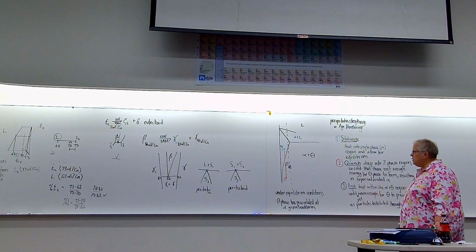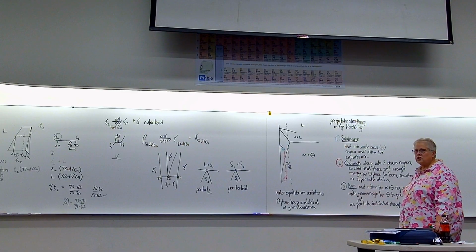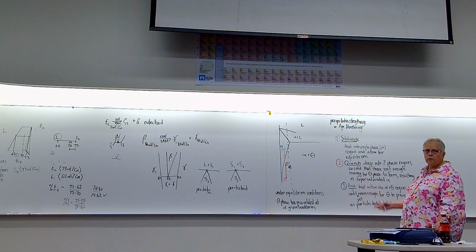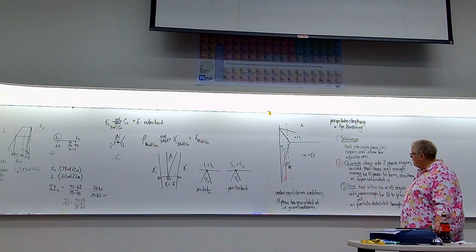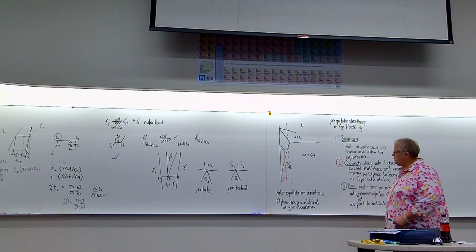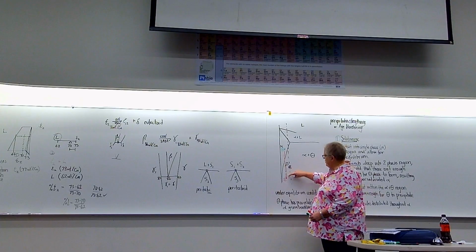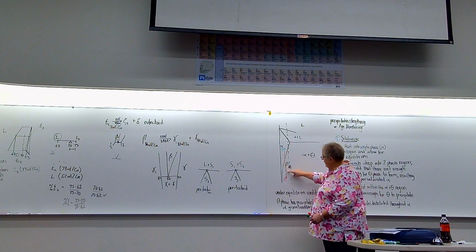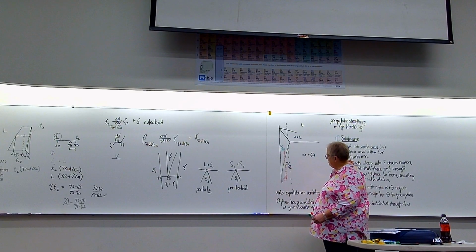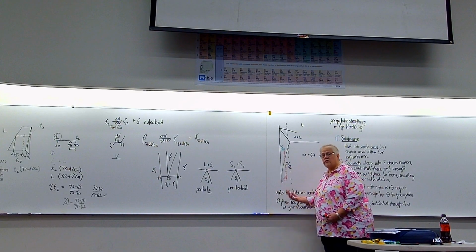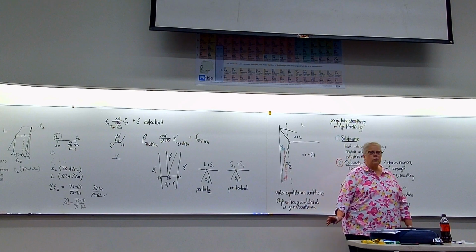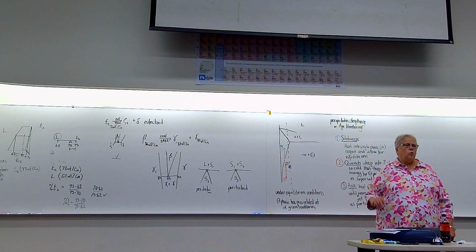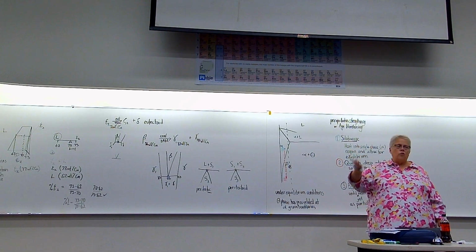Then quench, and quenching typically is just room temperature for aluminum alloys. And then the aging temperature kind of depends on what your composition is, but it's kind of up into here. It's still a ways away from the solvus. And after the aging's over, then you cool it back down, but we don't really call that quenching because we just want to stop that. That means everything's old.